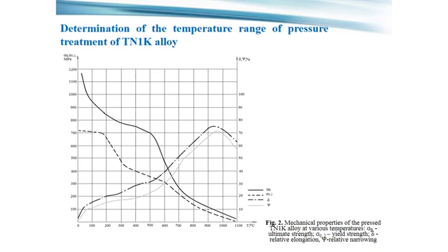Production and research of pressed rods made of nitinol alloys. Nitinol ingots were heated for pressing to a temperature of 1050 in order for the metal to be heated evenly. The ingots were placed in an oven at a temperature of 500 to 600 degrees and were heated together with the furnace at a speed of up to 15 degrees an hour to a temperature of 1000 to 1050. They were held at this temperature for 5-6 hours and then pressed at different pressing speeds.